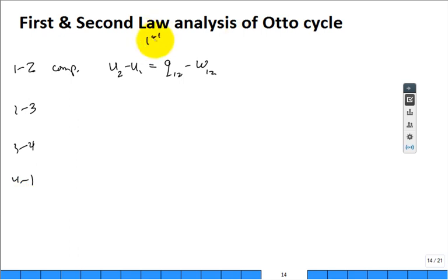Let's go ahead and write the second law. This is our conservation of energy. This is our second law, an entropy balance. Does it look like S2 minus S1 is equal to, now this is a little tricky, the integral of del Q divided by T? If you had a constant temperature during the process, I wouldn't have to put an integral there. It would just be Q1 to 2 divided by the T at which it transferred across the boundary. A lot of times we'll put a TB there. Fine. And then we have one more term, sigma 1 to 2. Hey, what is this sigma 1 to 2?